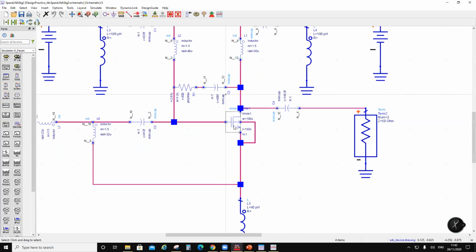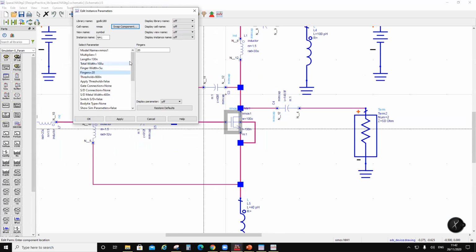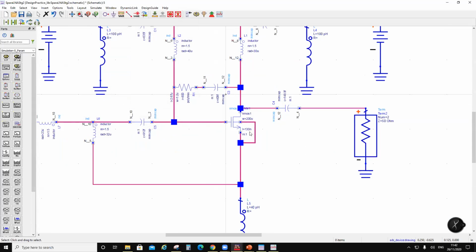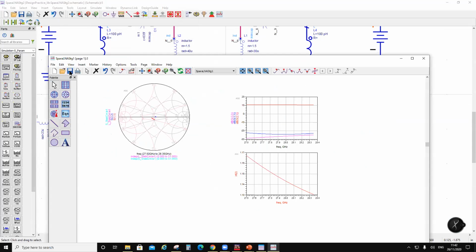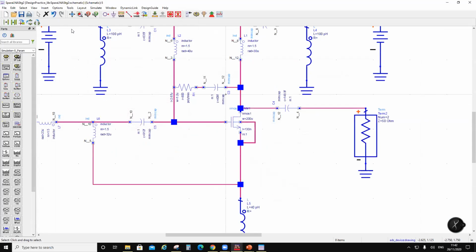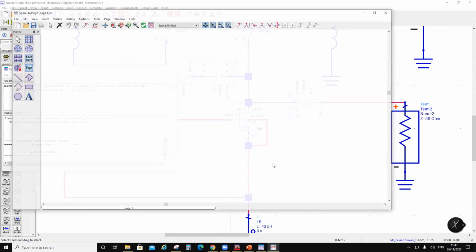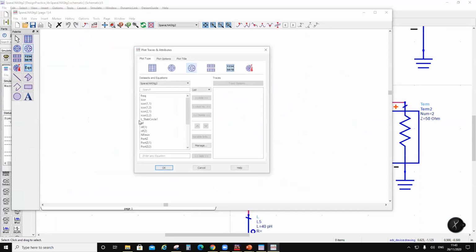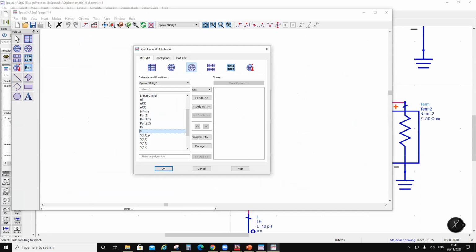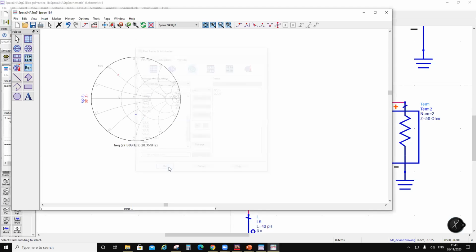Okay, and let's say I'm going to take this transistor to 40, so twice the size. Okay, and then I'm going to retune the stuff. So this window is for the previous one. So let's retune the stuff. I have changed this one. Let's look at the match. Okay, so I will look at S11. I will look at S22. So I'm over here. I'm mismatched now again.